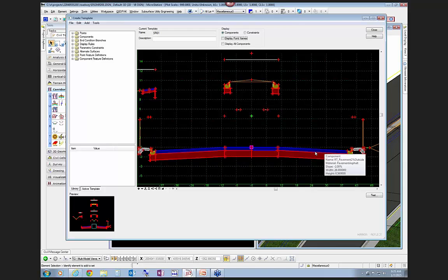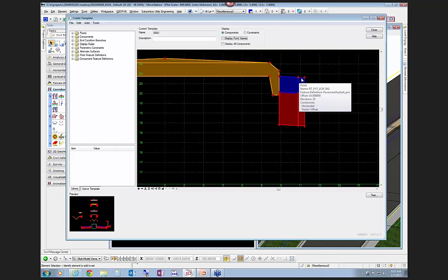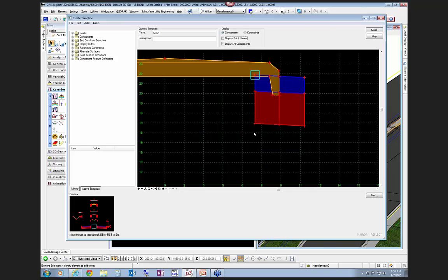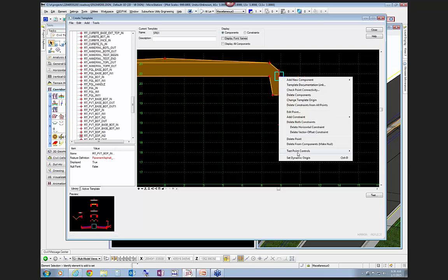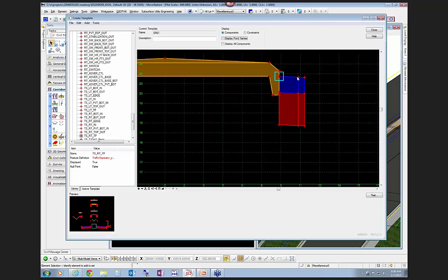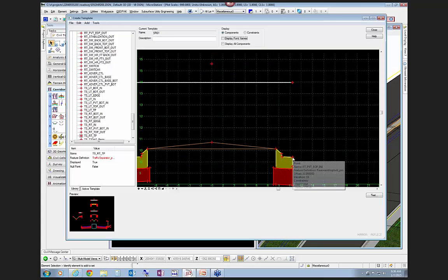And then in a traffic separator type component, you have the left turn lane, which is shown as really small here, but obviously if we did a test horizontal point controls, you see that it actually moves. It moves this whole thing, and it widens that traffic separator that way. And then the last little bit is the 2 points that line up with the points on the curb, which is these 2 points right here.